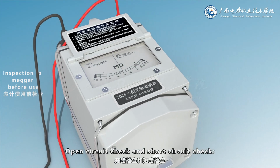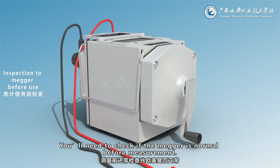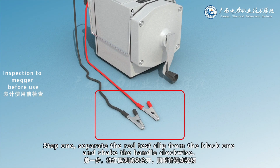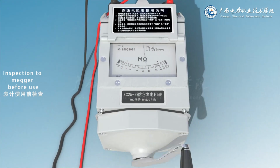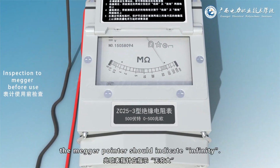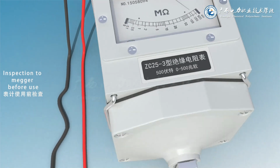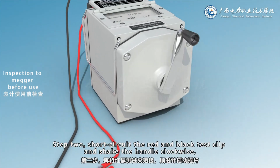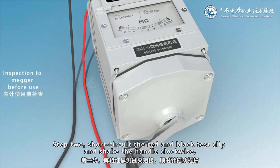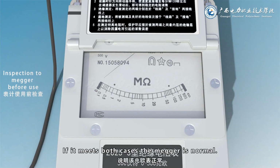Open circuit check and short circuit check. You'll need to check if the Megger is normal before measurement. Step 1. Separate the red test clip from the black one and shake the handle clockwise. The Megger pointer should indicate infinity. Step 2. Short-circuit the red and black test clip and shake the handle clockwise, the pointer should indicate 0. If it meets both cases, the Megger is normal.